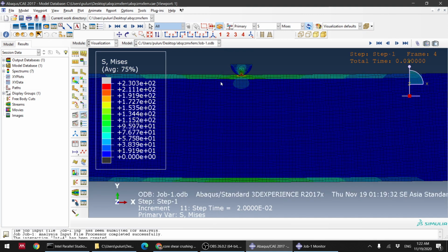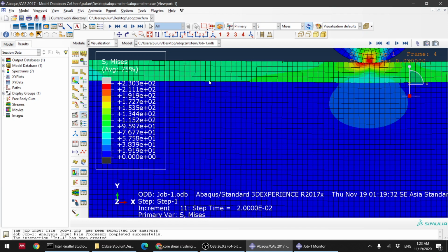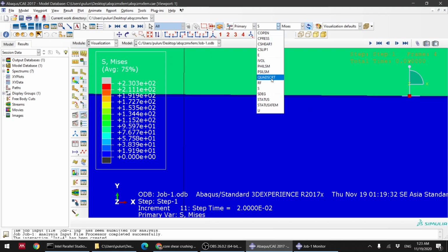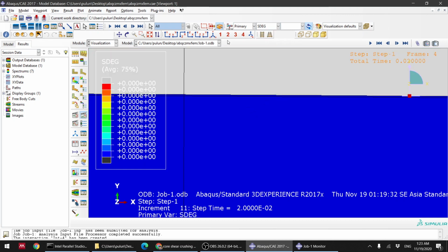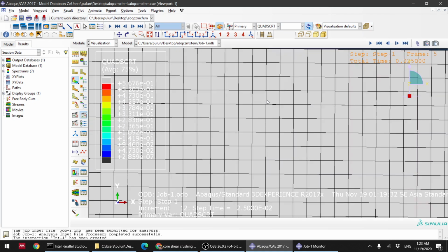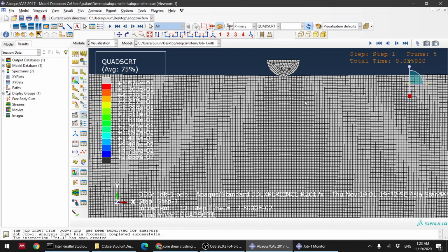We want to make sure that the crack appears using the extended finite element method and then propagates toward the skin, and then the cohesive element will start to activate. SDEG is still zero. So that area is still 0.3, about 30% of the starting point. I'm not sure where they will start.